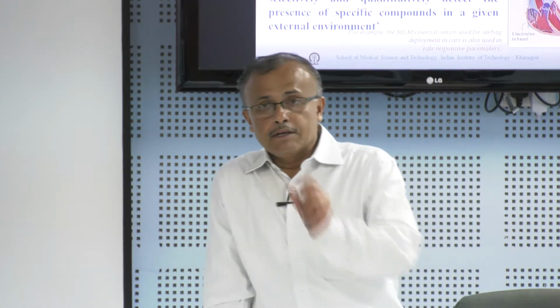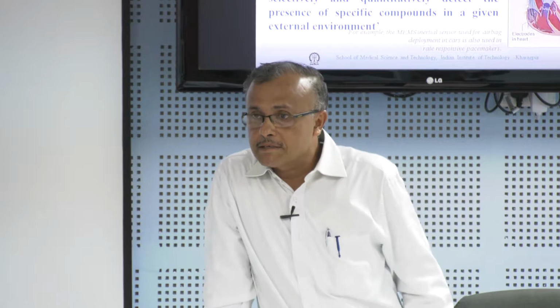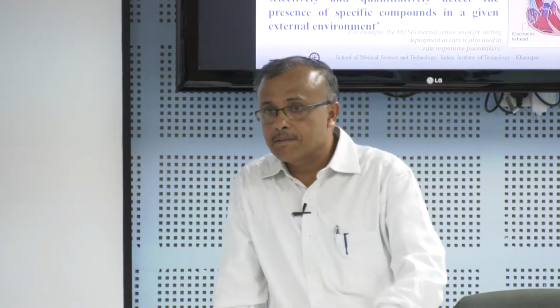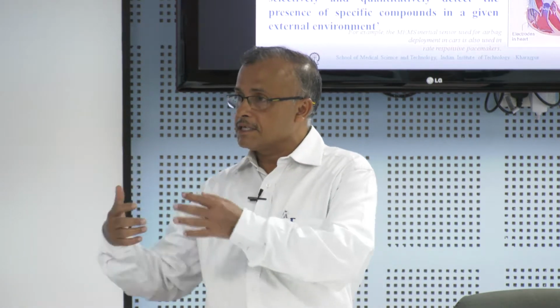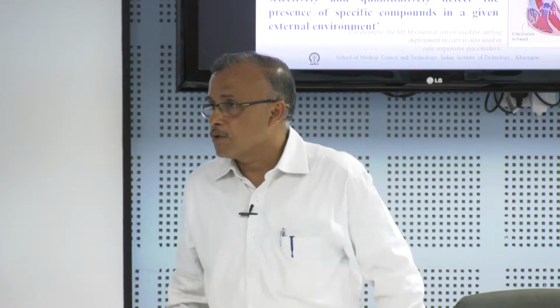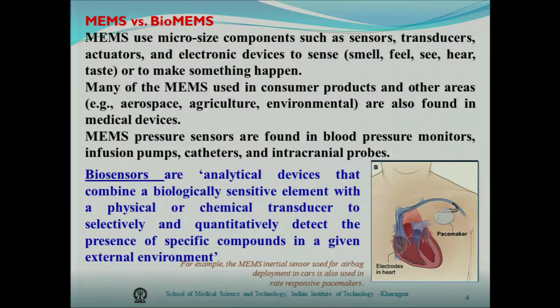So, by getting that delta R value, you can say which gases are present and how much. That is the very basic principle. Now, you can modify your material so that your range and sensitivity will change. That is the basic concept. Here, can I use gas sensors in medical devices? Yes, it can be useful, because for healthcare monitoring also we require gas sensors. And there these kinds of sensors are used.